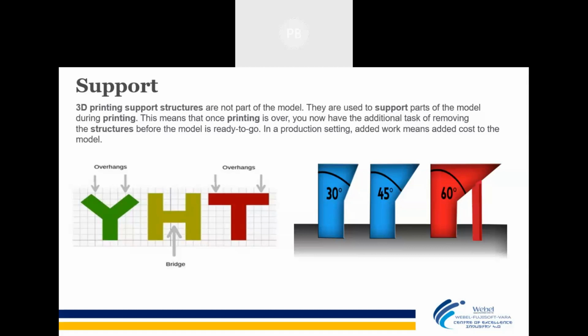200 layers. So whenever we are depositing 200 layers to get a model of 20 mm, you can understand the layer is very fine, 100 micron. Now on the slicer, if we put the layer height as 200 micron, how many layers do I have to deposit?